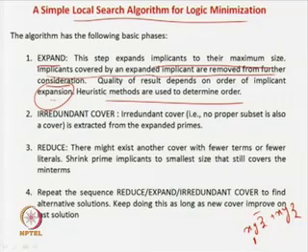That is again very important in a heuristic, that you are searching the next solution space. In this case, the next solution space is selecting a literal like x, y, z or whatever by which you are expanding. Should you start with x, should you start with y, and so forth. Depending on which one you try next, it will determine how fast you reach your solution. This is just like the example of a forest and a hunter I have given you. Which direction you should proceed next is also very critical in determining how quickly you get to a good solution. In this case there are also a lot of heuristic algorithms which will tell you, based on the previous results, which literal you should start expanding with.